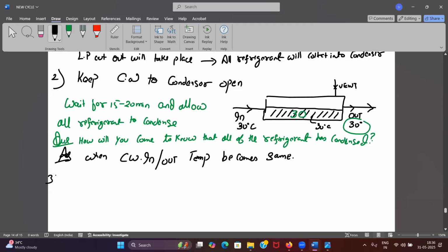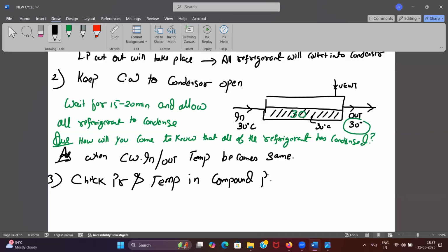Sir, first we have to connect the hose pipe to the relief valve, and another end will be connected to the recovery bottle, and with the help of vacuum pump, first we will remove all the air inside the hose, and after that, as the pressure is negative in the pressure gauge, we will open the relief valve. It will start taking all the air, and as all the air has been sucked out, the refrigerant will start to come out, and it will feel cool down. Yes, cold at that time, we will close the relief valve.